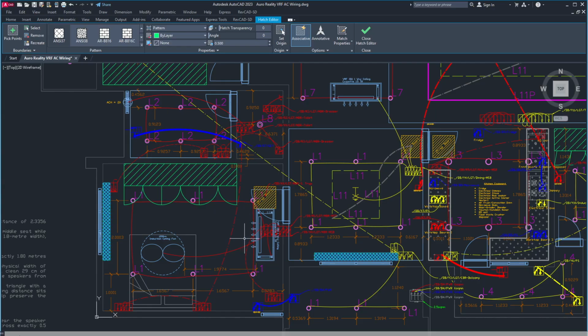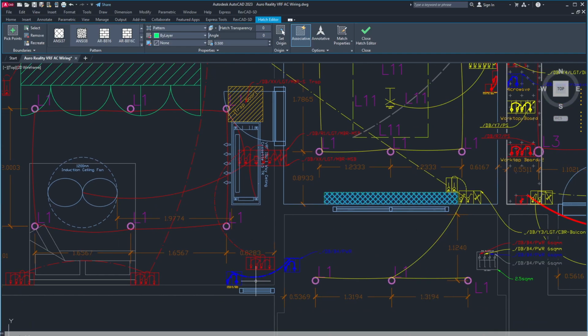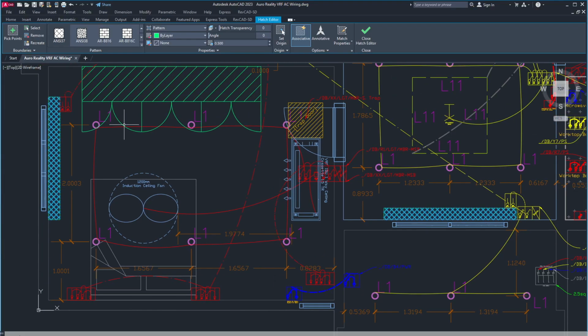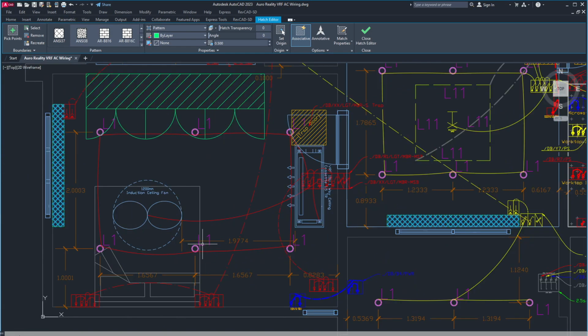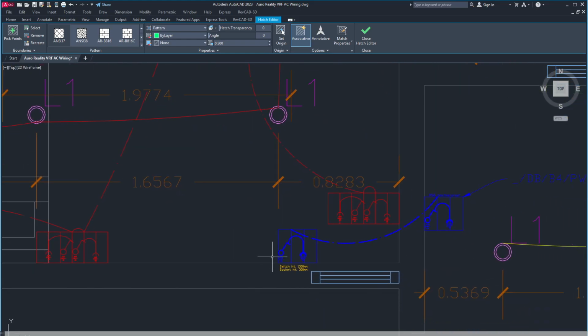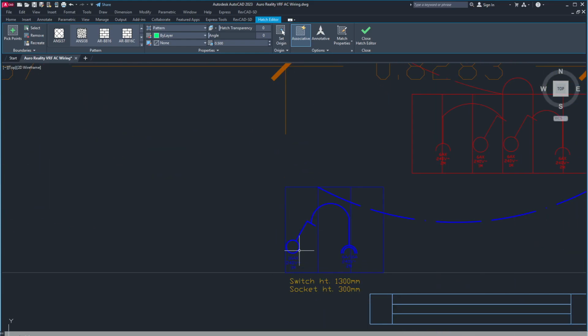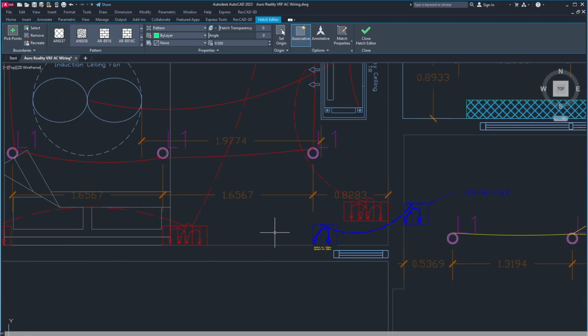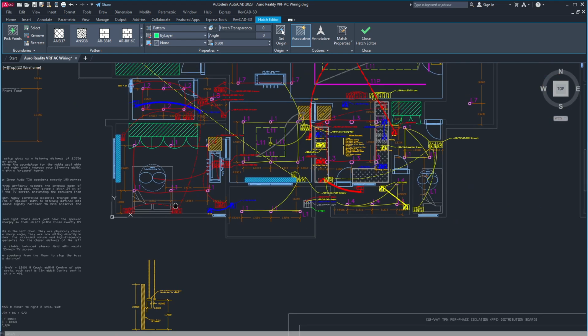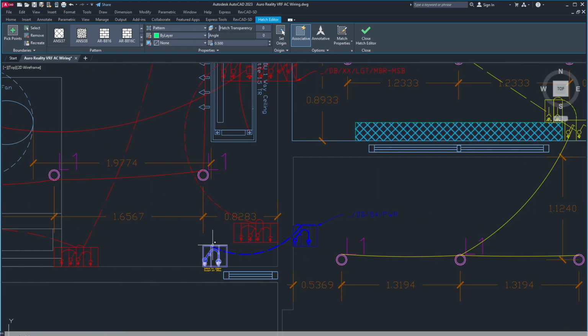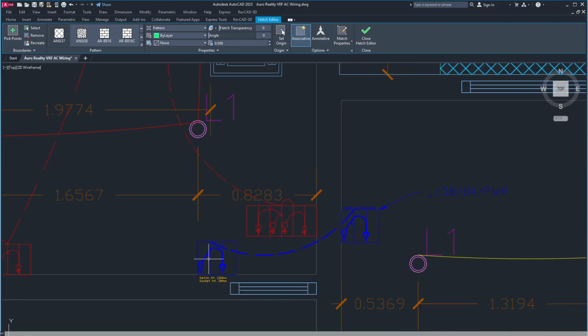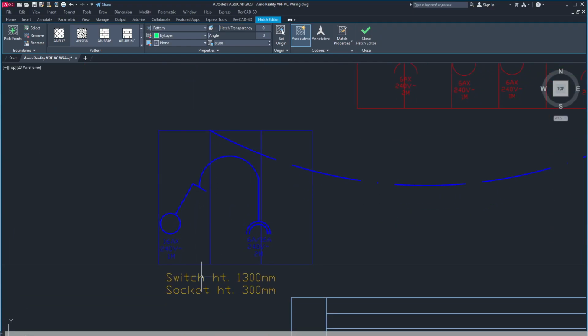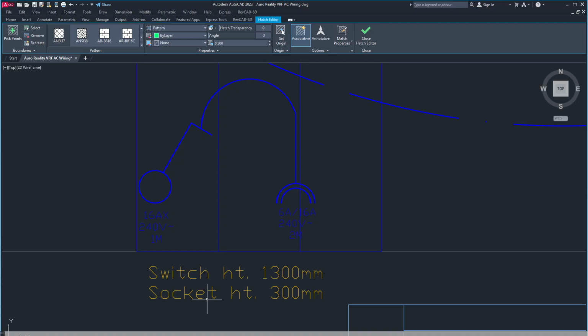Okay. And what else is there in this? Every room as per our Indian standard shall be provided with a 16 ampere socket. This socket will be used for vacuuming, cleaning, ironing or any other activity. So one socket you have to provide. This is a standard. So the switch height is 1.3 meter. Socket height is 1 foot from finished floor level.